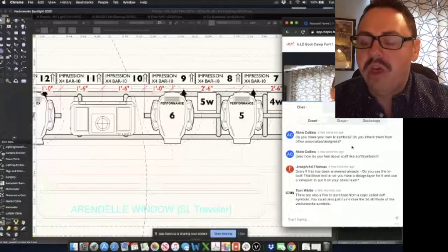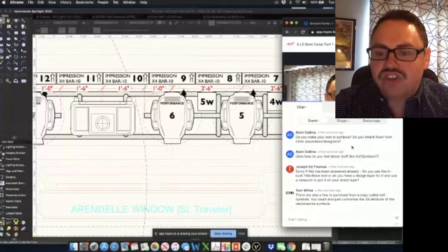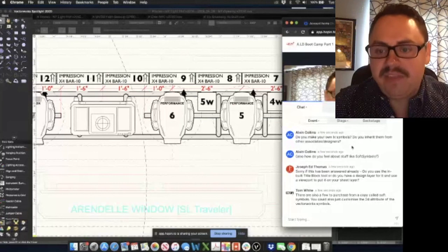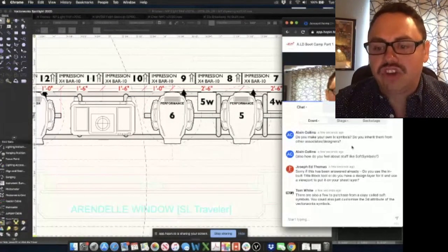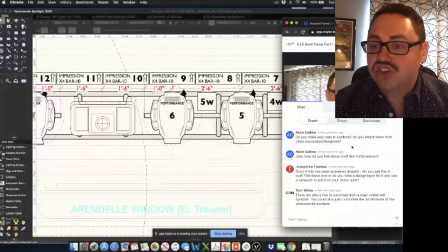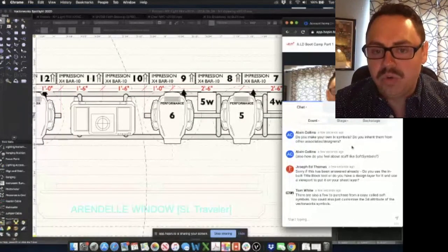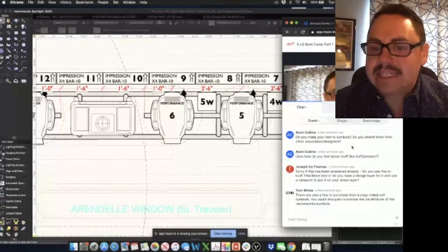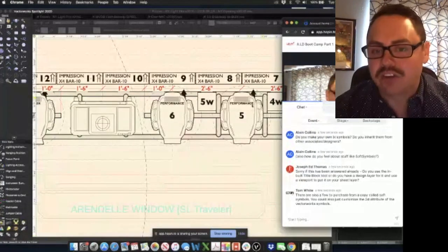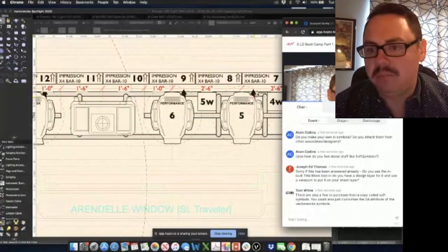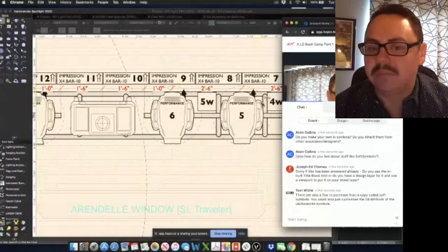I have done both. Most manufacturers now send out symbols. Vectorworks has a fantastic library that they update and send. There will be service packs that you can download and show new lighting fixtures as well. A lot of times in Broadway, I'm using brand new fixtures, and sometimes they haven't developed those yet. So sometimes I do have to draw my own. I also will take the existing symbols and add, for example, that arrow that I was talking about that shows the direction of the plug, which is not on most of their drawings. So I will add that in myself.